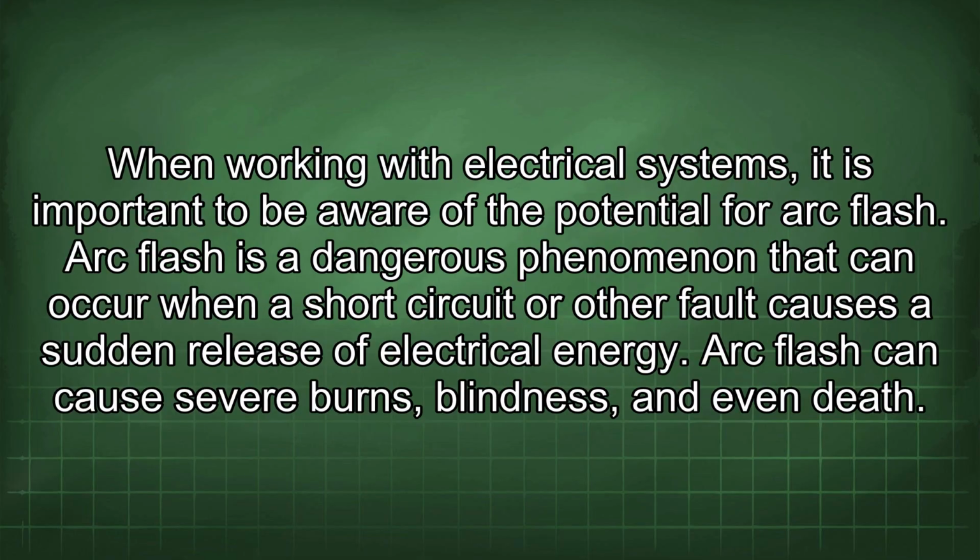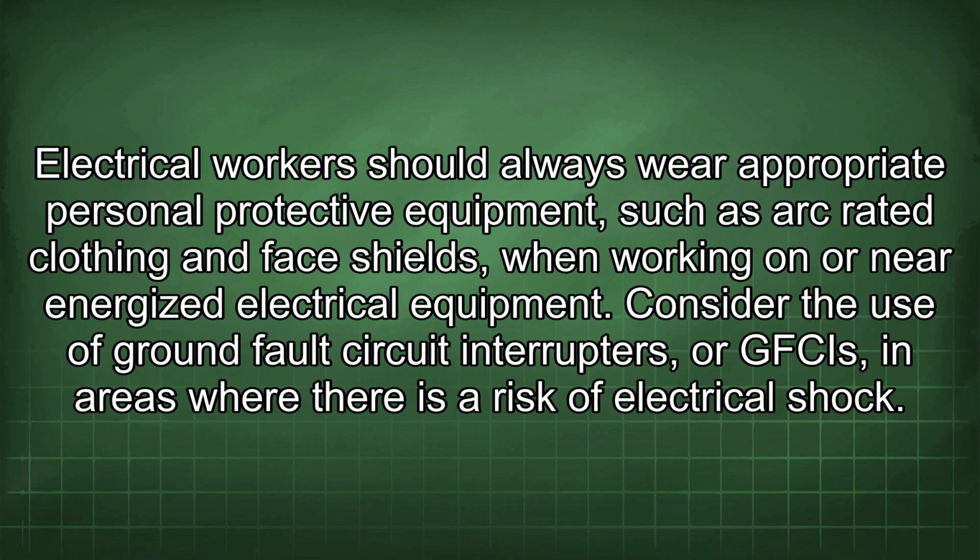When working with electrical systems, it is important to be aware of the potential for arc flash. Arc flash is a dangerous phenomenon that can occur when a short circuit or other fault causes a sudden release of electrical energy. Arc flash can cause severe burns, blindness, and even death. Electrical workers should always wear appropriate personal protective equipment, such as arc-rated clothing and face shields, when working on or near energized electrical equipment.